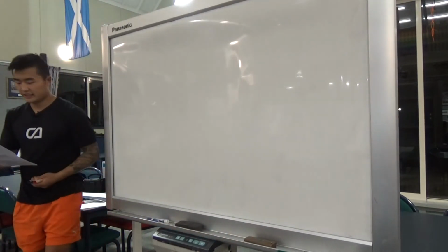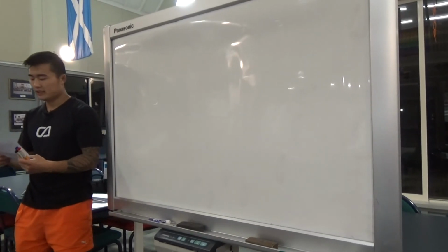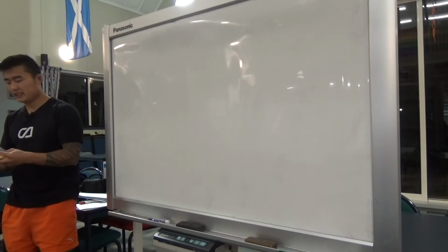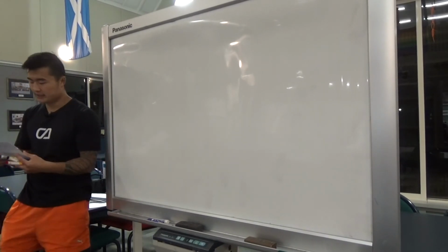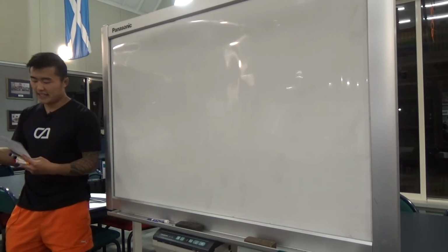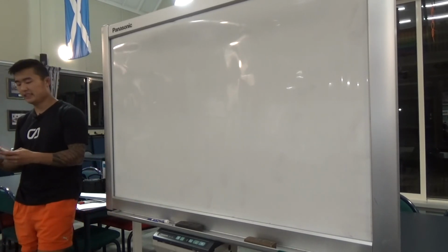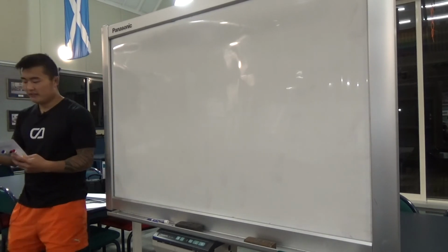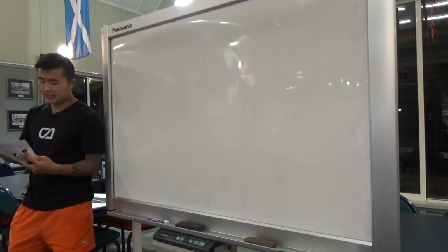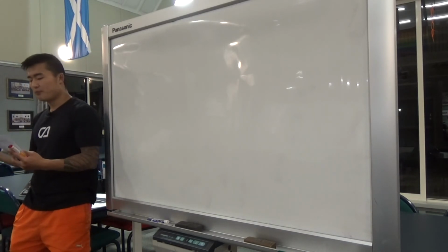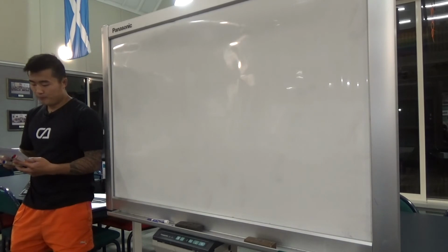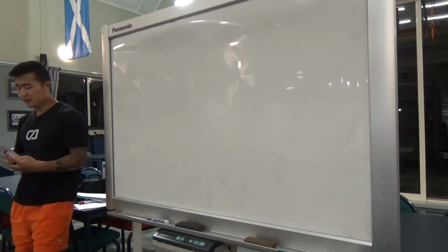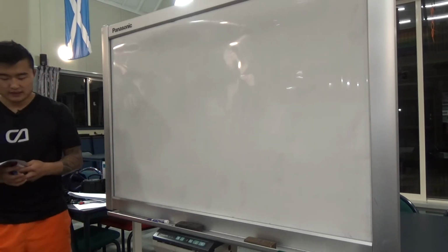Number 10, we have a rigid sealed container with a volume of 1 meter cubed, and it contains a monoatomic ideal gas. At a temperature of 20 degrees Celsius, the gas is at a pressure of 100 kilopascals. The container and gas are heated to a temperature of 55 degrees Celsius without any change in volume and with no leaks. So again, we're having a change in our conditions, right? So we're changing our temperature in this container. And we want to find out what the new pressure is in the gas after the temperature increase. So that's going to be the final pressure.